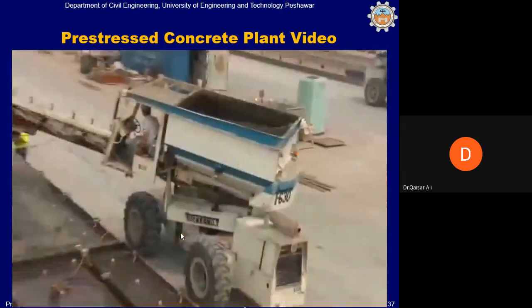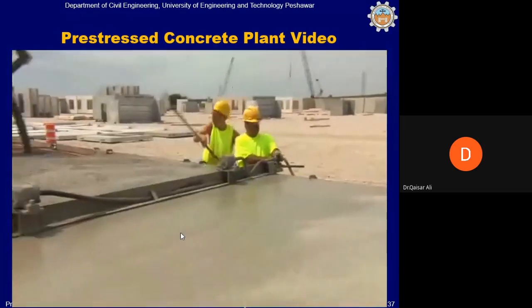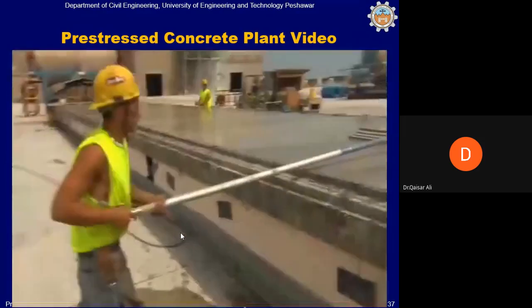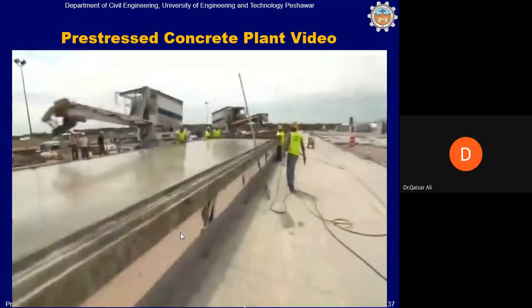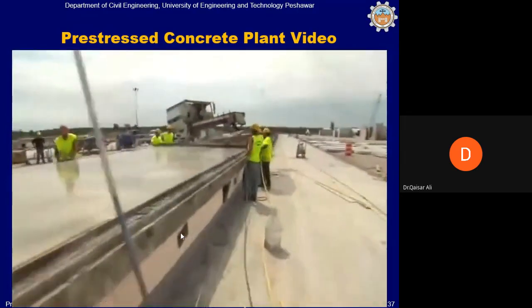Back at the bed, the concrete placement continues. A vibrating screed is used to level the surface evenly. A bull float is used to finish the surface. An evaporation-reducing spray is also being applied to the surface to minimize the potential for plastic shrinkage cracking.